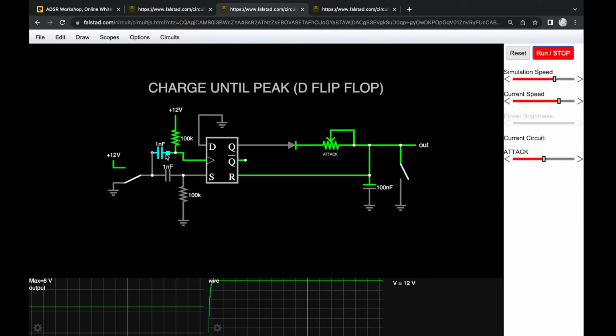And this means that for a split second, current can flow into the capacitor, right? Because the pressure here drops, so we have a little bit of room to jam current into this capacitor. And because we have a resistor here, for a very, very short second, the voltage here actually drops, and it drops to 0 volts, interestingly enough.